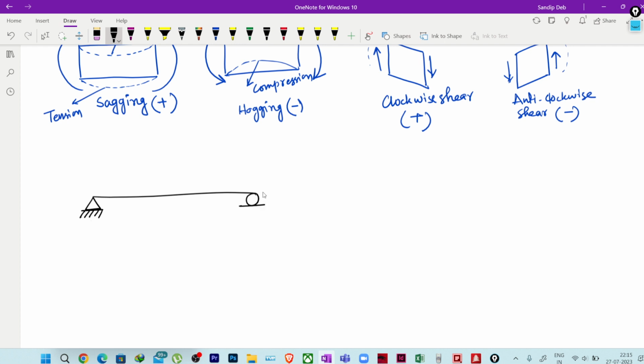Okay, roller support means it can move along this direction like a roller. But the other direction is restrained. I should say, as it is a 2D plane, it will move only along this and this axis, x and y. Correct. So the other direction we should not consider, and as it can rotate, there will be no moment restraint also. Correct, because it is kind of simply supported.